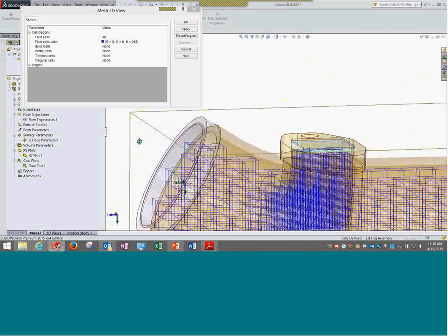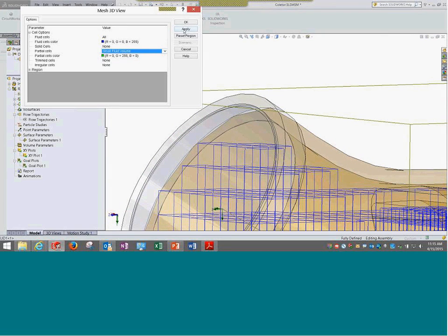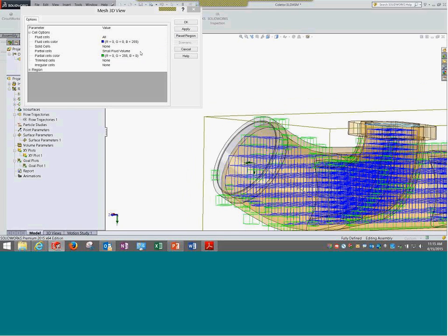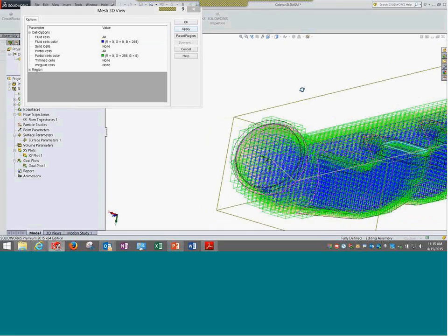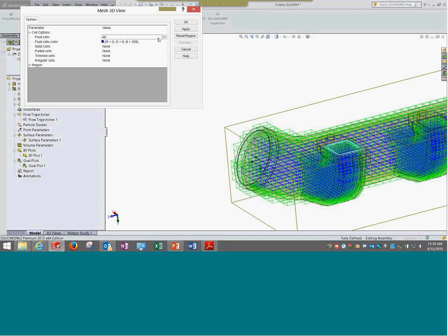Saying that, it is also not covering the entire region, but there is something called partial cells, which will help. Let me check if it is here. So this will ensure it is covering the entire geometry, and it does not mean that if it is overlapping a solid and a liquid, it is not covering. But the partial cells have the capability wherein a certain part of those elements can behave as a liquid, and a certain part can behave as a solid. That helps in ensuring that.